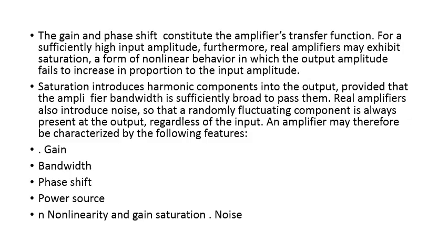The gain and phase shift constitute the amplifier transfer function. For a sufficiently high amplitude, the real amplifier may exhibit saturation, a form of nonlinear behavior in which the output amplitude fails to increase in proportion to input amplitude. The saturation introduces harmonic components into the output, provided that the amplifier bandwidth is sufficiently broad to pass them.